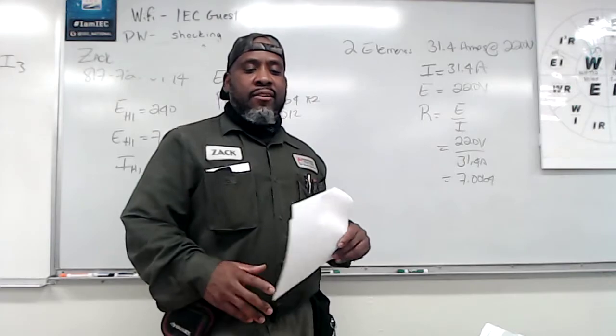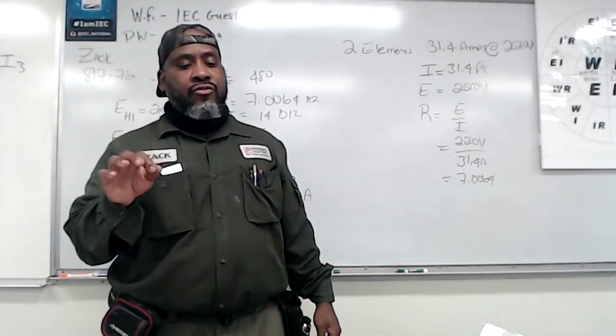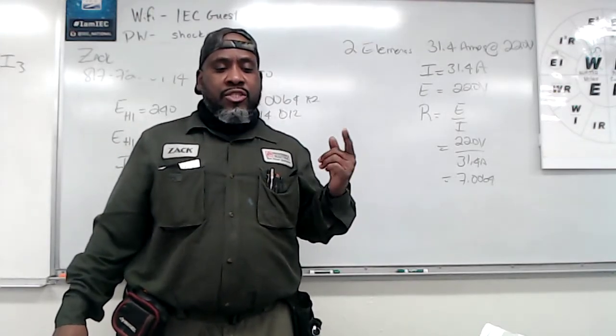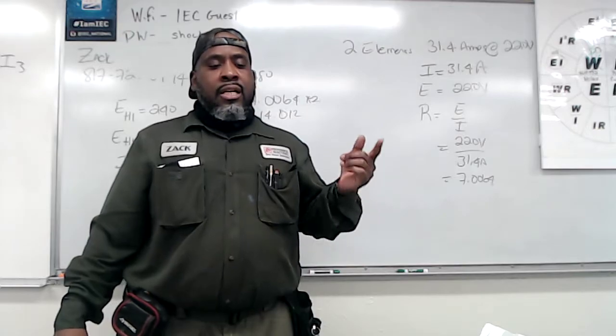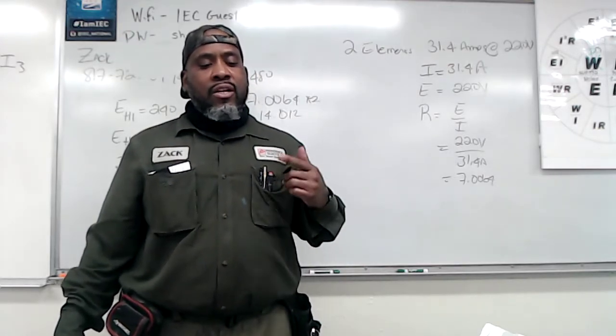Refer to the 119.102 drawing. Which of the following are true? The left half of the receptacle is connected to circuit 22 and is switched with the left switch. The other half of the receptacle is connected to circuit 22 with constant hot. The luminaire is connected to circuit 24 and switched with the right switch.